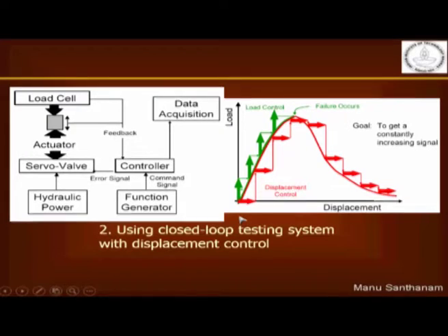How do we do that? So what we see is to give a certain level of displacement, what is the load required? Okay. So you know that when concrete starts cracking, it will get more and more displacement. Displacement will increase when concrete starts cracking. So what we try to do is reduce the rate of loading at that point. When the displacement increases tremendously, we reduce the rate of loading. So for the same increment of displacement, I keep measuring my load.